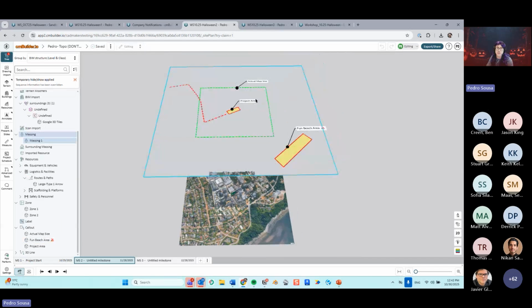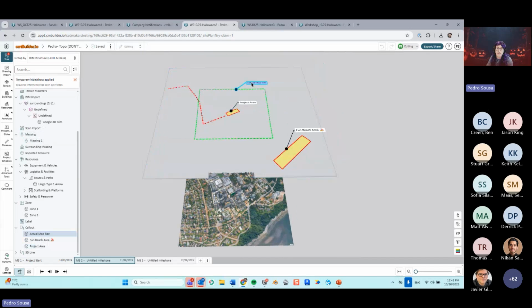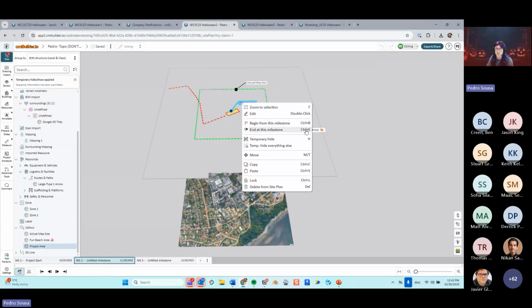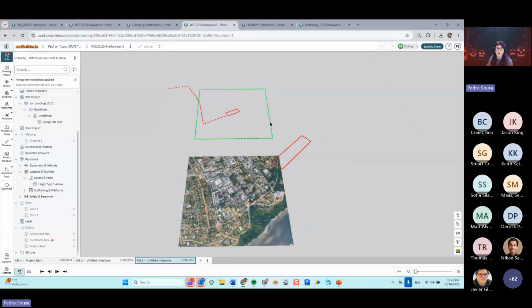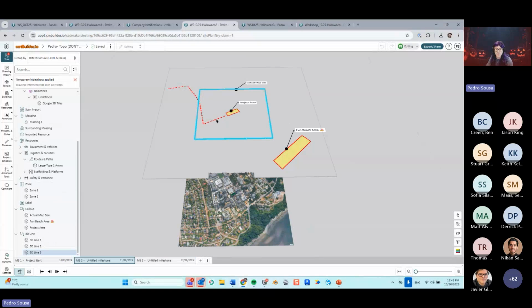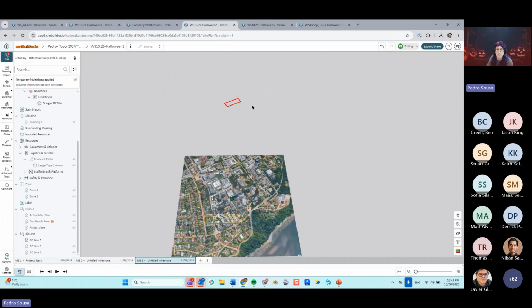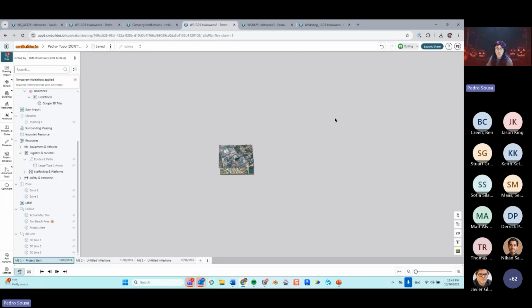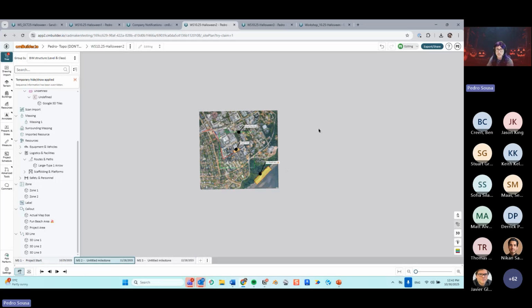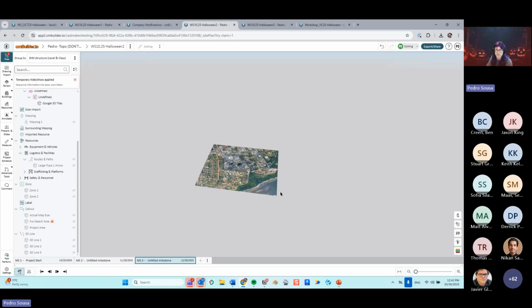I'm selecting these objects and hitting my Control E shortcut to make them go away at the next milestone, as you can see. So this is an interesting way to do things quicker, just for that milestone, and then the next one doesn't have the elements that you don't want. Cool. Now you have a view where this is bigger than the rest.